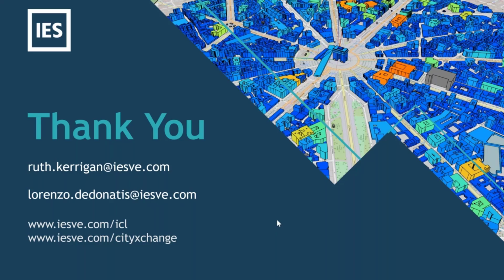Yes, basically, this is why once you start creating your baseline model, every energy modeler starts from, okay, let's first build the geometry of the building and use the standard loads for that particular building, either coming from ASHRAE loads, or CIBSE standards, or whatever standard is used in that particular region. So the unregulated loads are something that are above that standard. That standard won't take into account, for example, if you have, just a stupid example, an office with 3 fridges in a small office. That's something that you as a modeler need to account for, if you have the possibility to do.